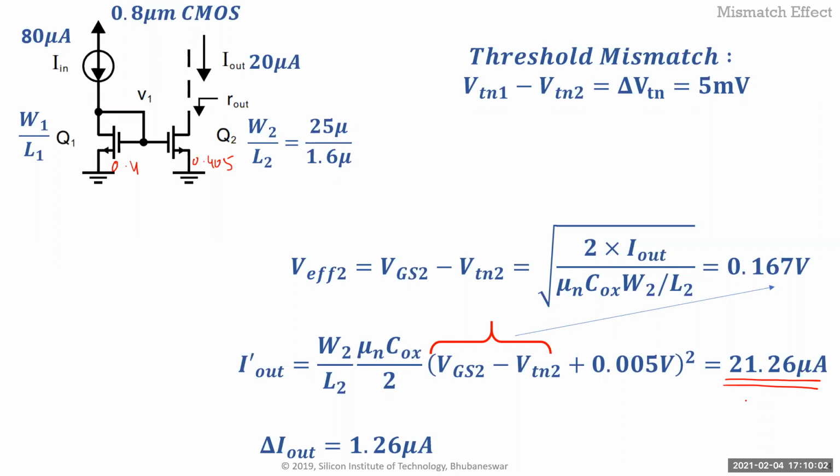And how do you negate the mismatch? So these are foundry parameters. They will give you some mismatch where it's delta VT over the square root of the area of the transistor. So you have to calculate that before. If you can't tolerate it, you just have to keep increasing the area of the transistors. There's no other way. I mean, there are ways, but then your architecture becomes complex. So you start doing chopping and all that stuff. If you want to do brute force, you just keep increasing the area of it.